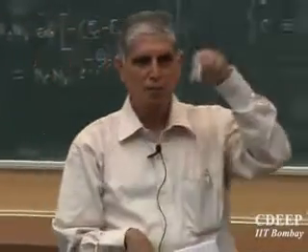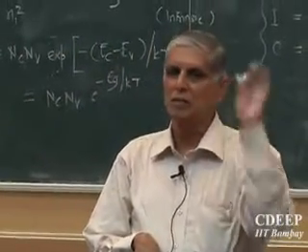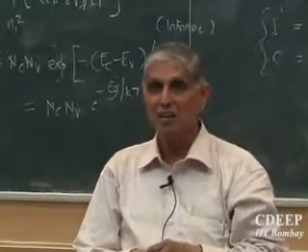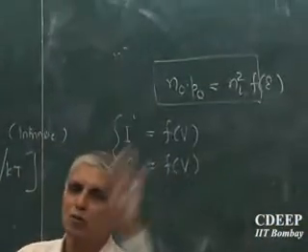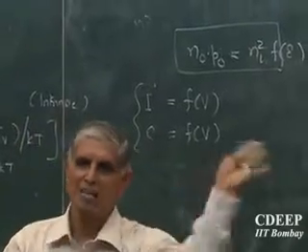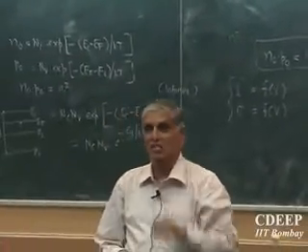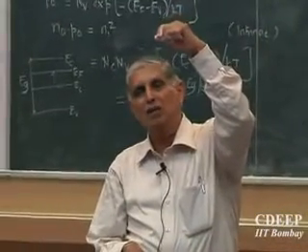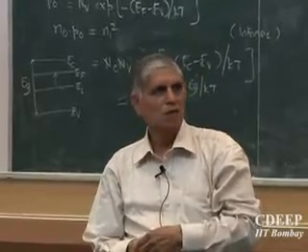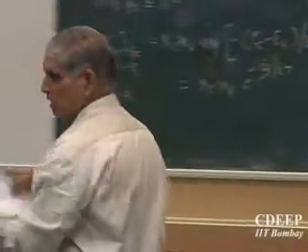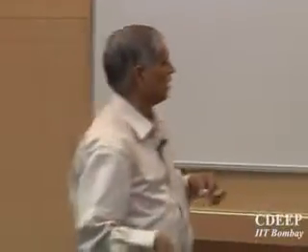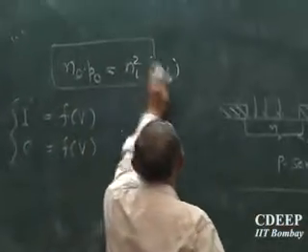So as I keep increasing the impurities, first it will compensate things there, and then if I add further N, it will become N-type. Is that clear? If I exactly add N equal to P throughout this material, the material will become intrinsic, because it will cancel out. Now this point is very interesting. A certain number of electrons I am creating because of the donors. That is N-type. Thermal generation was also going on, and I must keep that in mind. Use this equation here.